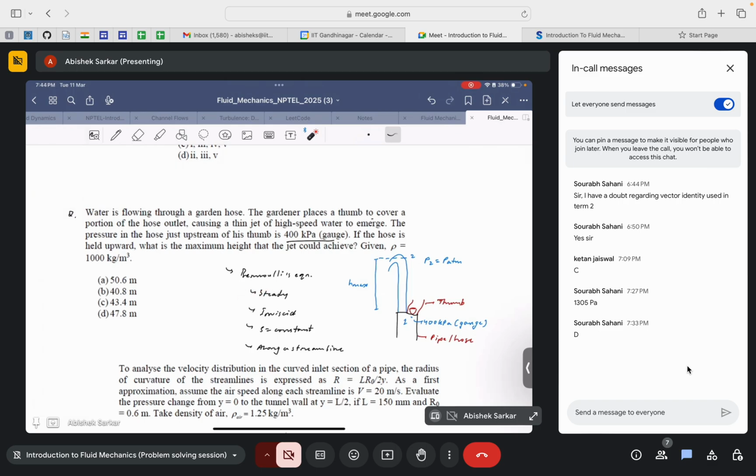First assumption is done. Then I can say that, of course, it's difficult to assume the flow to be inviscid because water itself has a finite viscosity. But given that there are no walls binding the flow and no wall present to generate any kind of velocity gradient along this particular jet of water, we can say the flow is inviscid, because there is no velocity gradient available.